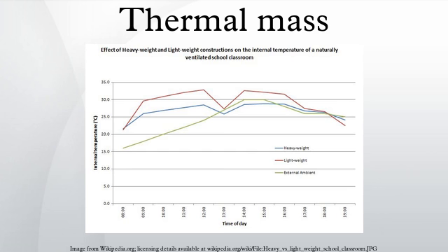Temperate and cold temperate climates, solar exposed thermal mass: thermal mass is ideally placed within the building and situated where it still can be exposed to low-angle winter sunlight but insulated from heat loss. In summer the same thermal mass should be obscured from higher-angle summer sunlight in order to prevent overheating of the structure. The thermal mass is warmed passively by the sun or additionally by internal heating systems during the day. Thermal energy stored in the mass is then released back into the interior during the night. It is essential that it be used in conjunction with the standard principles of passive solar design.